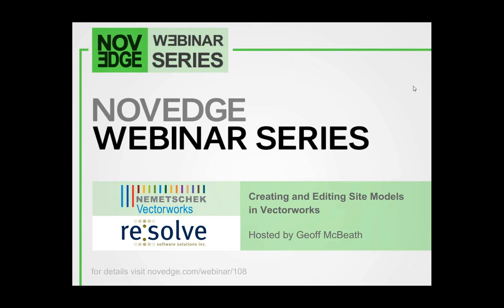For this week's webinar, we're teaming with Canadian distributor Resolve Software Solutions to cover the steps for creating a 3D site model from a surveyor's file, including geo-referenced data, alignment with air photos and DWG info, as well as cleaning up edges and problem data points after creation. After the existing site model is created, Geoff from Resolve will look at site analysis and the use of modifiers to create the proposed site.